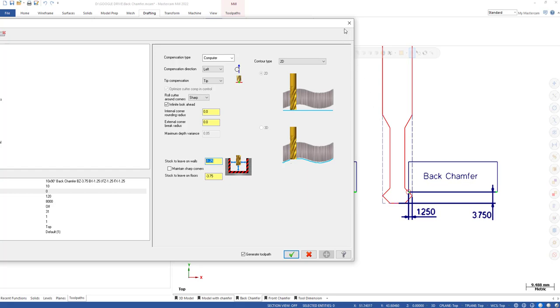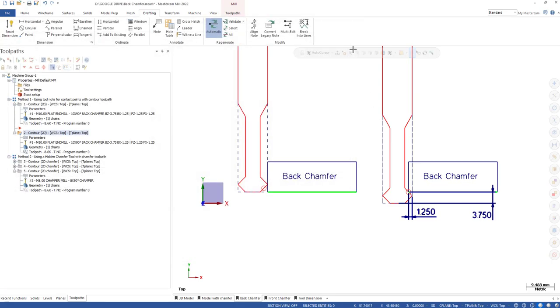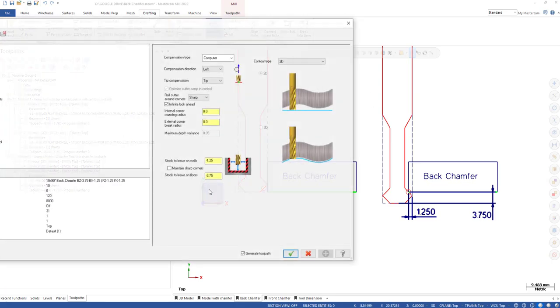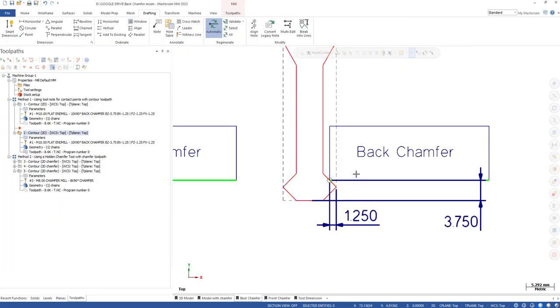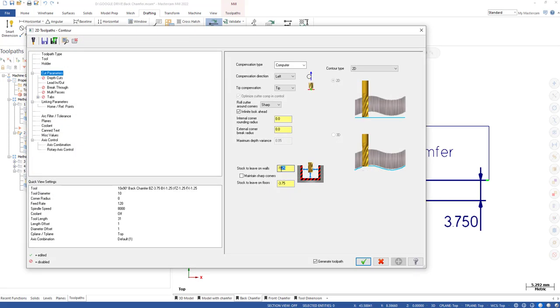Yeah, very easy. So you just measure it one time and write it down to use later. This number just makes the tool contact the part. So if you want to make a chamfer, you need to adjust this number a little bit, depending on how big you want the chamfer to be. So if you want a 0.2 chamfer, it should be 1.45 instead of 1.25.